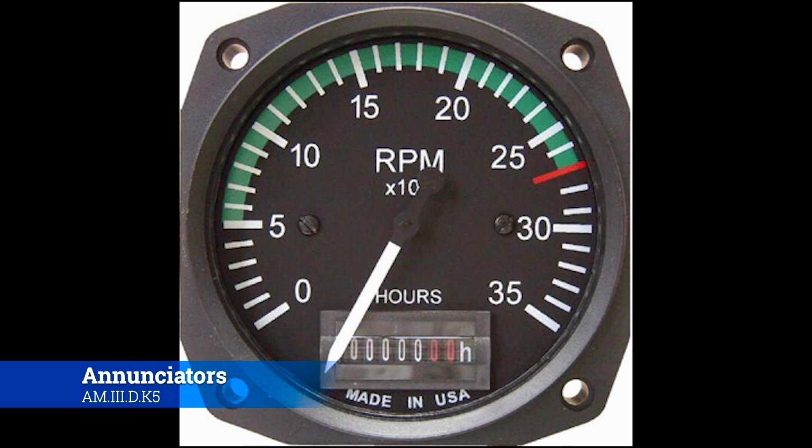Now, why the range? Well, the range will depend on the quality of air that's coming into it. It's not turbocharged or anything like that; it's just got a downdraft carburetor that's sucking in the outside air and into the engine, and then the engine just produces whatever power it produces. If you have a really hot, humid day that's not good for performance, it might be closer to that 2,300 mark. But if you're on a really nice, cool, crisp, dry day, then it might be closer to the 2,575 mark. So there is a little bit of range there.